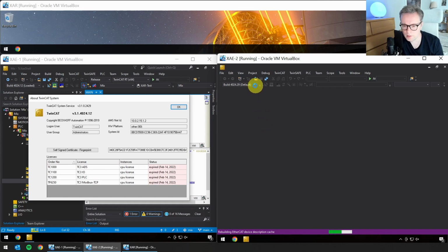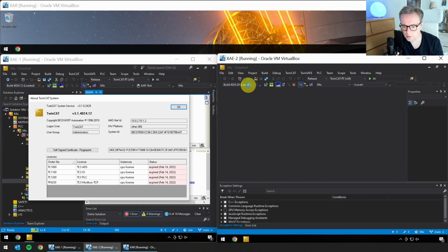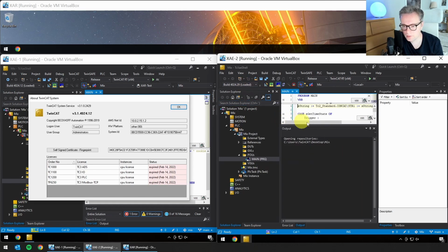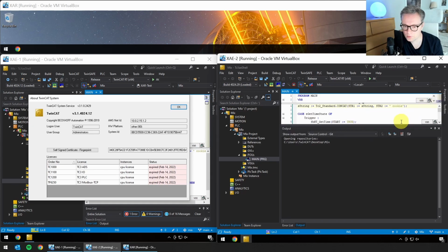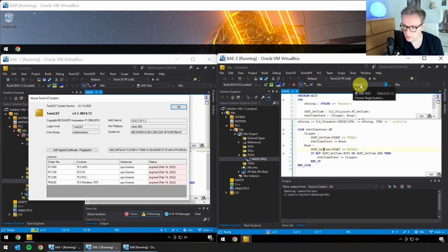So what you can see here is the remote manager, and it's with this that you can actually select which version of TwinCAT you want to be loaded before you open the project. But now I just double click the project and then it automatically selects the latest version that is installed on the machine unless you specify otherwise. But if you go here now, you can actually see that we have both 4024.29, which is the loaded one, and 4024.12. Before I show you what to do about this, I will simply log in to the target.